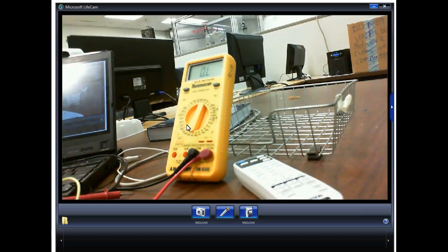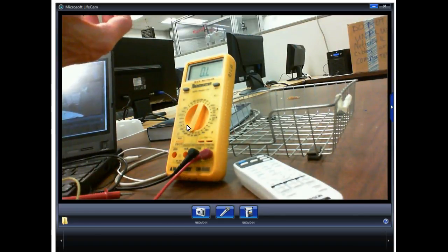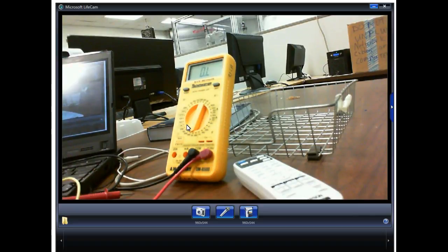And so what's the advantage with common collector? We have a high input impedance, right? And we have a low output impedance. We don't get any voltage gain, but we get a lot of current gain. And these are used to drive high current loads, like speakers. Speakers are looking for current because they generate magnetic fields, right? They have a very low impedance.